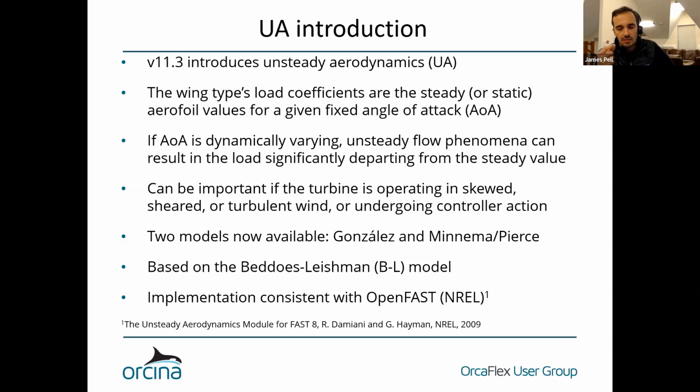So to address this, we've added two models, Gonzalez and Minnema-Pierce, and they're both based on commonly used BL models. And the implementation in OrcaFlex has been adapted from the work done by NREL for the OpenFAST AeroDyn module. So the credit for the models goes to the guys at NREL, and of course also the original authors for which these models have been named.